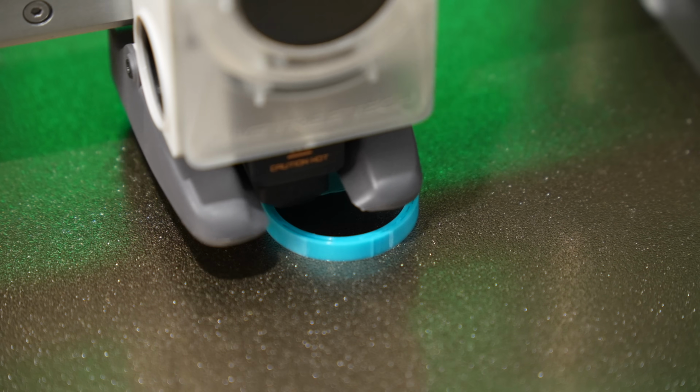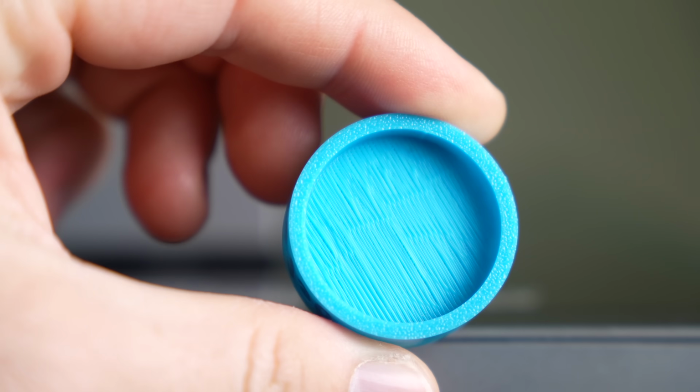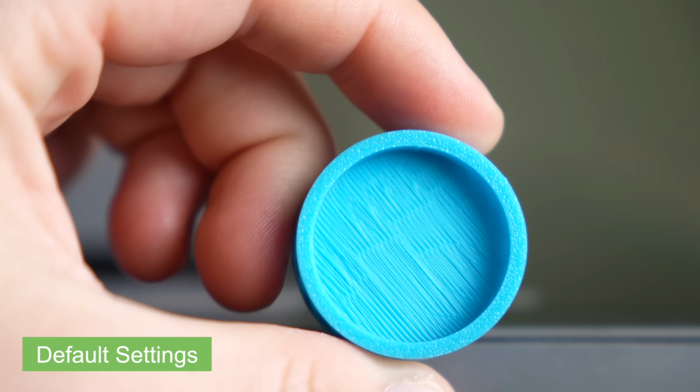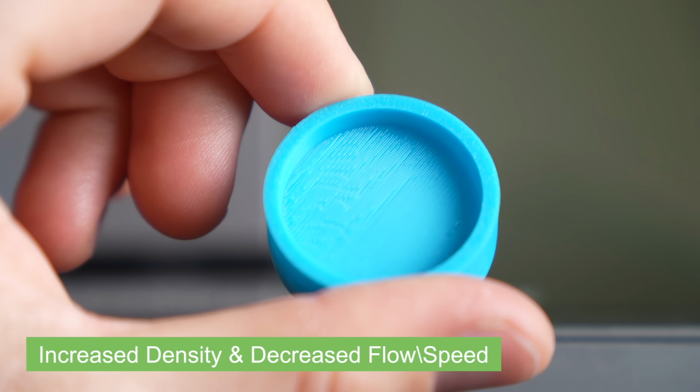Pair that with a slightly lower flow ratio and some speed tuning, and you can get some really clean bridges. From the starting point and using just the default settings to adjusting the density, flow, and speed, I was able to eliminate the gaps between the lines pretty easily with just a bit of tweaking.